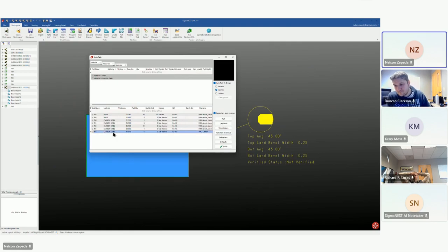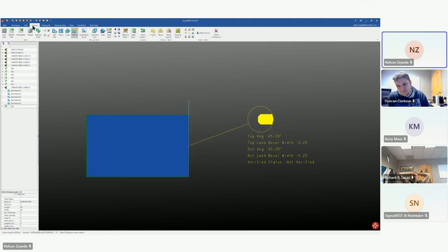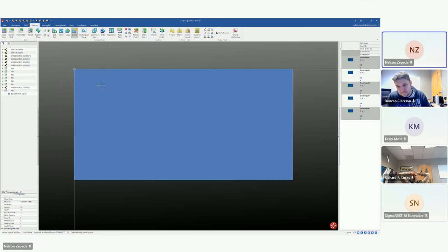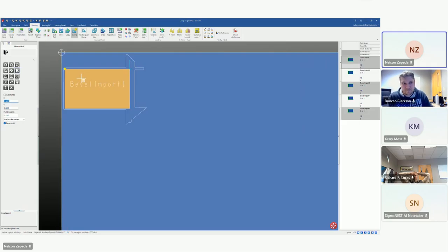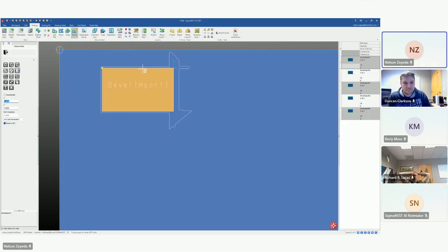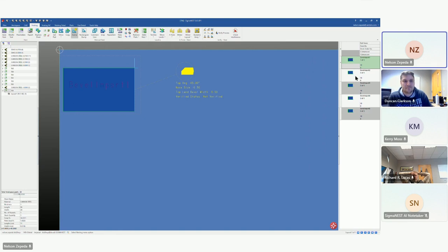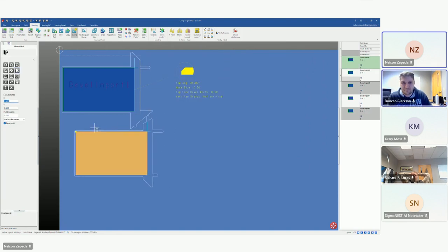And let me get my test I created for my bevel parts, and we'll look at the bevel ones here. And again, for beveling, there's nothing special I have to worry about for nesting. It takes it into account automatically. So it recognizes it's a bevel part and it's on my bevel machine. So we need to add in my clearances there for all of my corner loops and all of that for beveling.